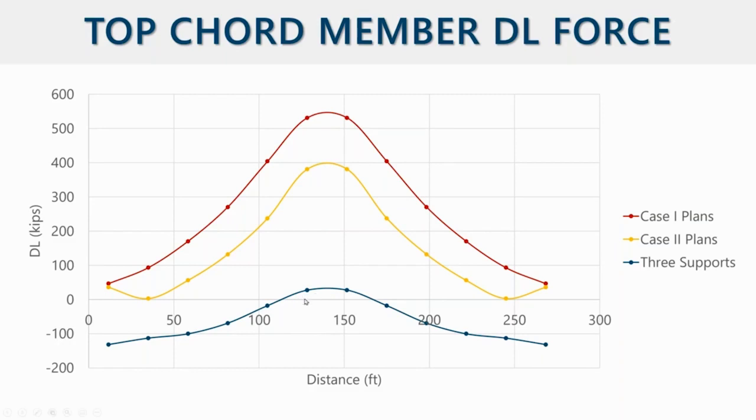And at the bottom, the blue line is when you apply 3 supports at the beginning. You can see how much the difference is in terms of force. So if we just treat this movable bridge as a normal bridge, just applying those 3 supports at the beginning, you can see the difference. Actually, I have seen people do it in that way. And unfortunately, this is incorrect. And what makes it worse is that this is actually on the unconservative side. Look at how much we underestimate the dead load.